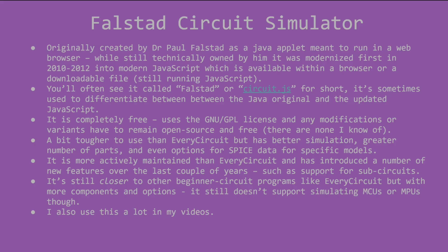It can be a bit tougher to learn than Every Circuit since the interface and the animations aren't as pretty, but it has a better simulation, a far greater number of parts, and even options for using SPICE data to create specific models. It is still very actively maintained with new features coming out. Somewhat recently, they introduced subcircuits, so you can basically make your own parts.